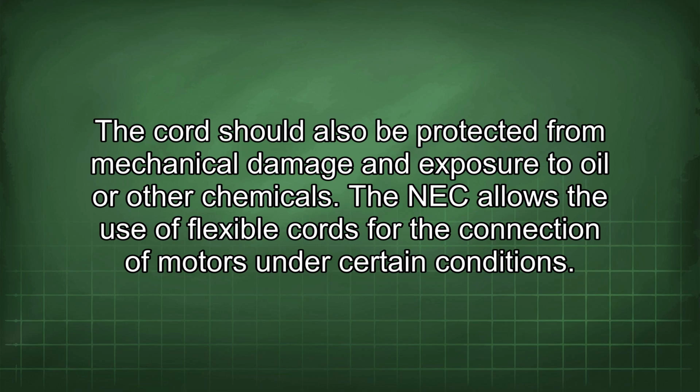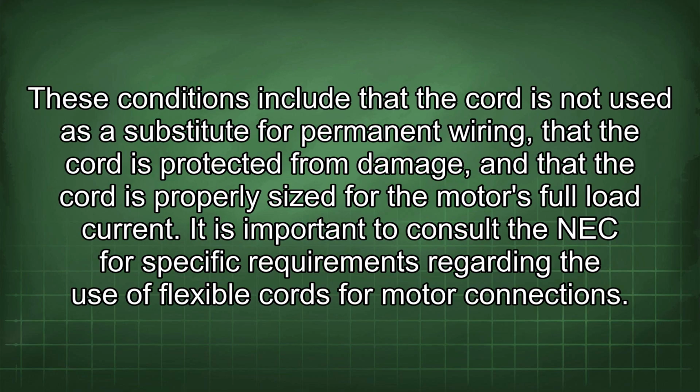The NEC allows the use of flexible cords for the connection of motors under certain conditions. These conditions include that the cord is not used as a substitute for permanent wiring, that the cord is protected from damage, and that the cord is properly sized for the motor's full load current. It is important to consult the NEC for specific requirements regarding the use of flexible cords for motor connections.